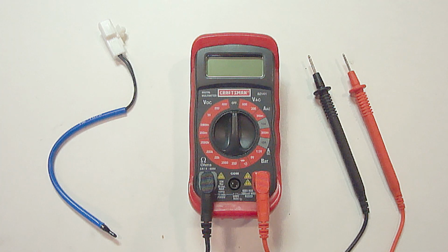If you're able to gain access and remove the sensor, then you can use a digital multimeter to check the function of the sensor. These sensors use resistance or ohms output. As the sensor cools down, the ohms go up. As the sensor heats up, the ohms go down. Also be sure to check for voltage and corrosion at the electrical connection that plugs into the sensor.